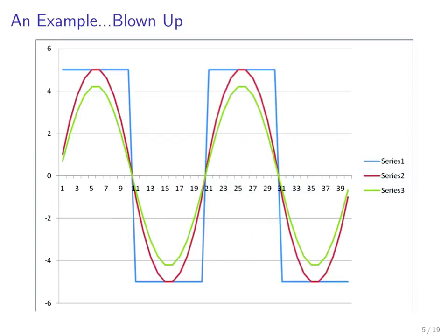And here it is blown up so that you can see that, with filtering once, again, we have reduced the signal slope, and with filtering twice, we reduce it further. You can see that the more filtering we have, the closer the filtered signal is going to come to 0. So we're going to come closer to the mean value of the signal, which is 0, right? The mean value of a square wave is just 0 over time.